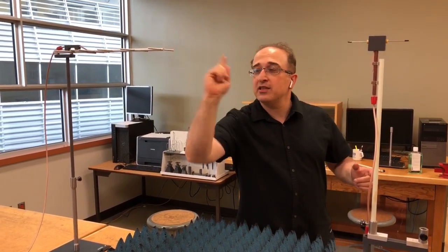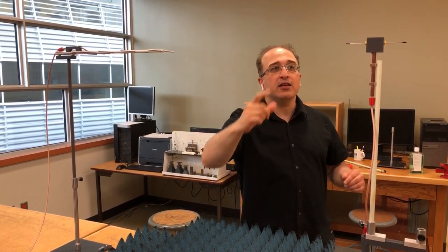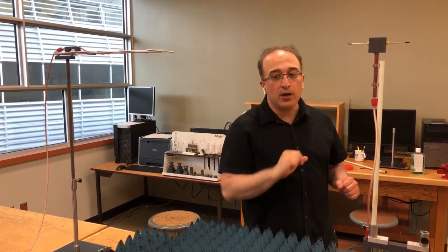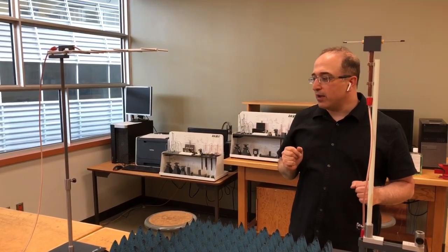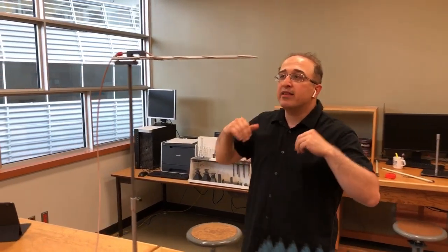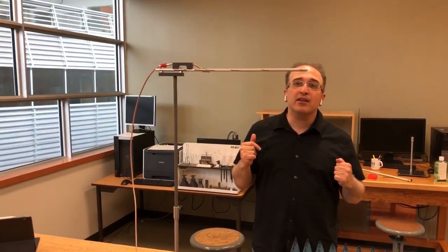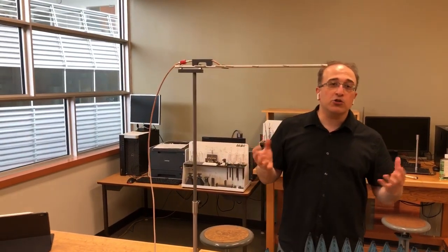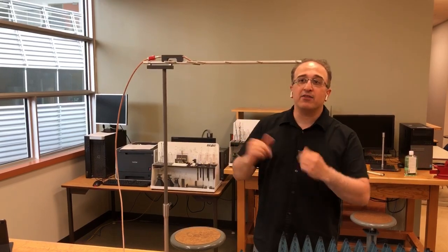So this transmitting antenna was transmitting linearly polarized in this direction, and this dipole antenna was matched to receive linearly polarized wave. But now I want to keep this in E-plane, but then change the polarization of our transmitting antenna to vertically polarized, so that I have polarization mismatch between the receive and transmit.